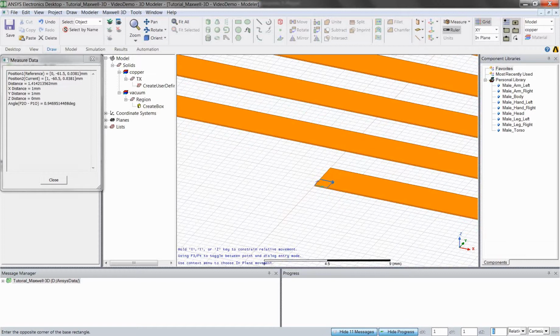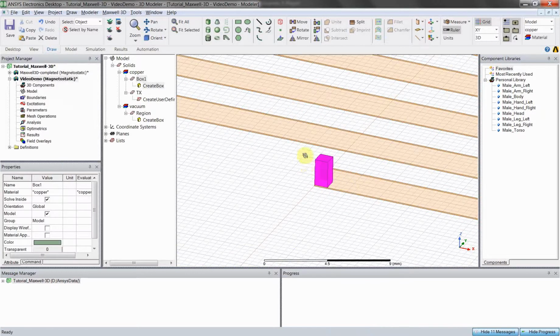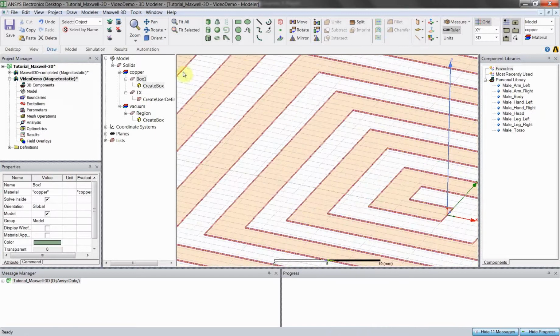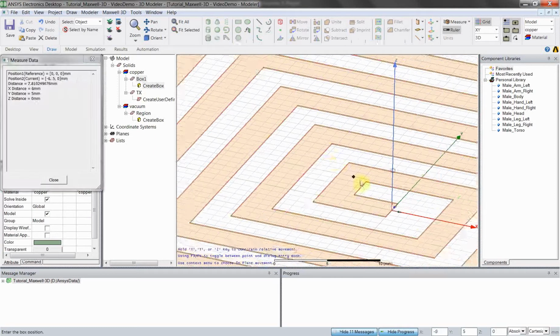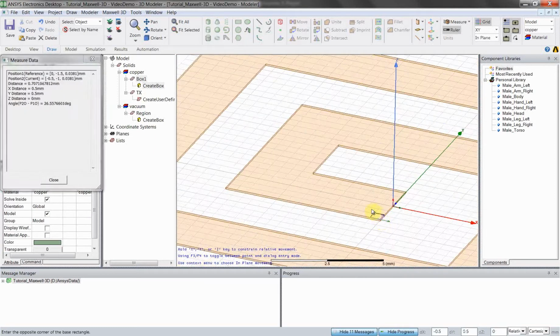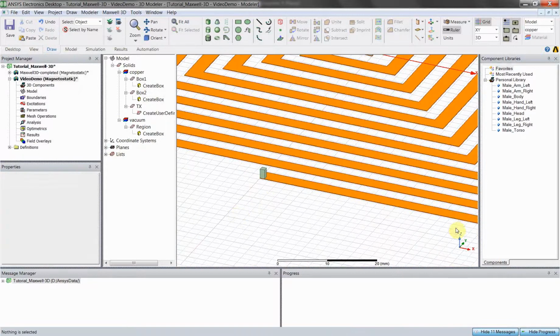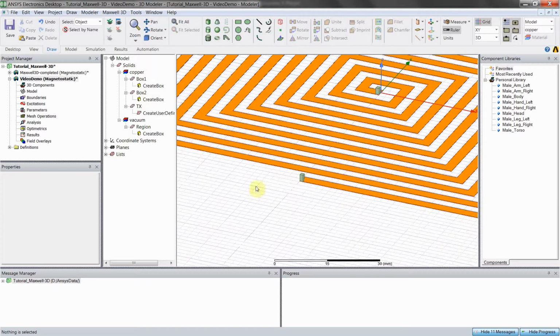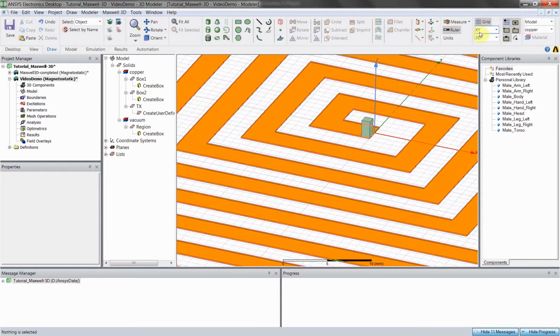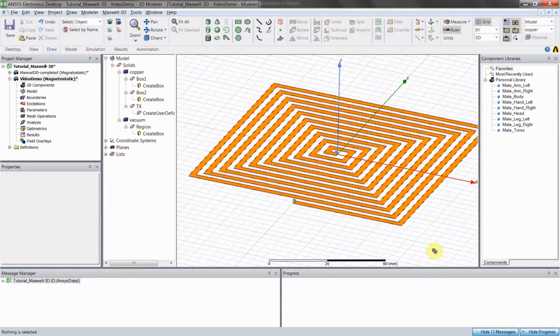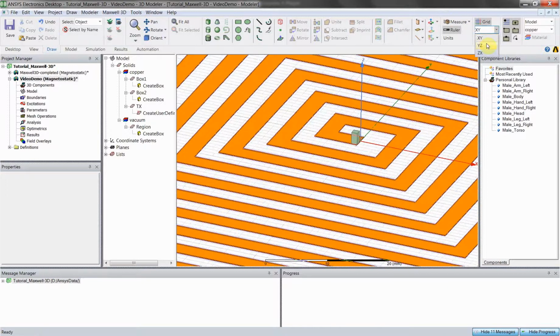Let's say it's 1 by 1 by 2 millimeters, and then we're going to have one over here, negative 1 by 1 by 2, sorry. And from that, we're going to extend them to the negative y, because that just seems kind of intuitive. That will be where these leads are flying back to. So we just have to generate that really quick. We're going to want to make this in the XZ plane.